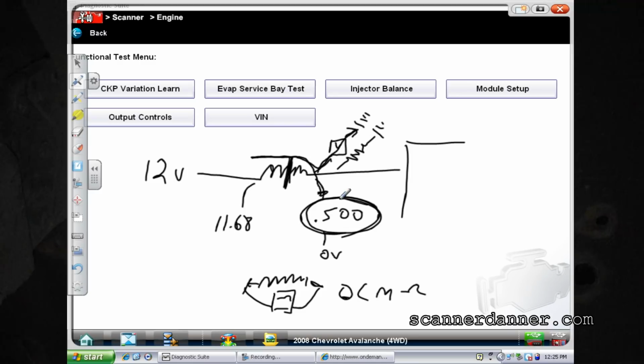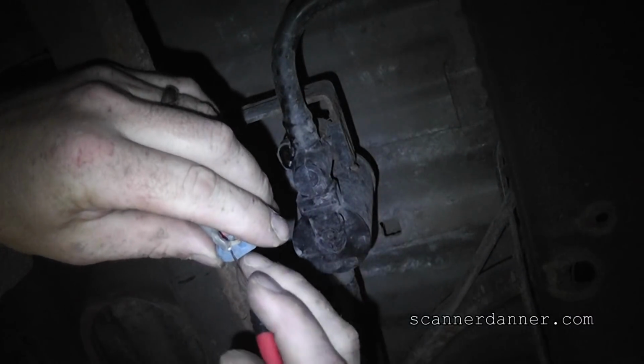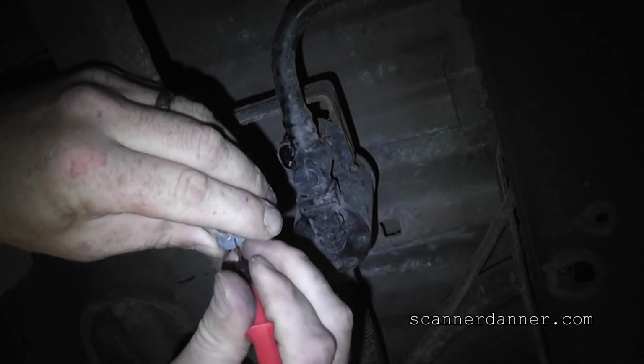Either way, we might be overkilling this open solenoid. I just want to address where that 500 millivolts was coming from. Robert mentioned maybe it was ghost voltage. Absolutely could be, because it is an open circuit. But it was pretty steady. Usually ghost voltage jumps around. Let me go back to this and show you one more voltage measurement. I'm just going to back probe the control wire now with it unplugged with my voltmeter again.